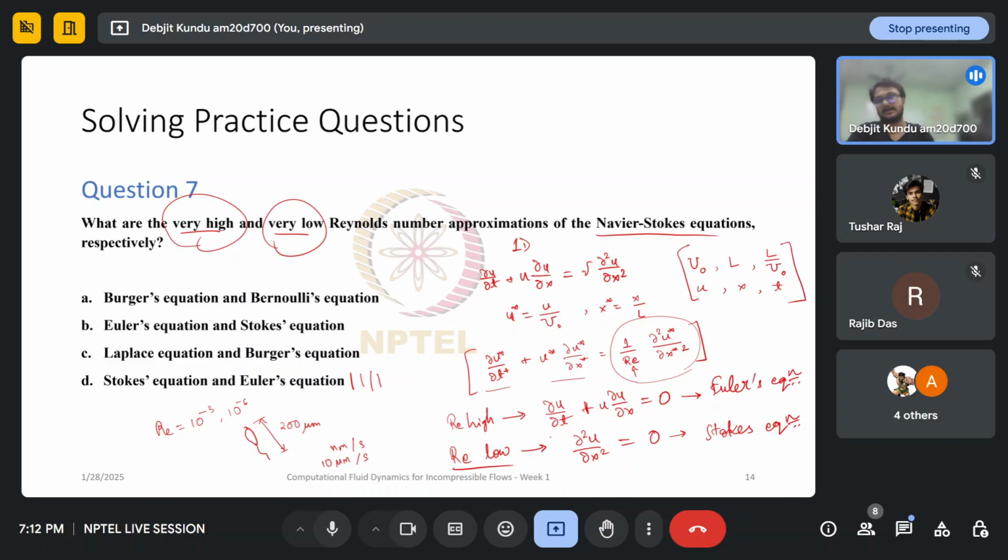So basically, due to these approximations, we don't have to worry about the full Navier-Stokes equations, which have more terms and are more difficult to solve. If we can smartly ignore a few terms which are less important, we get these simpler equations which are easy to solve, even when you're applying CFD.